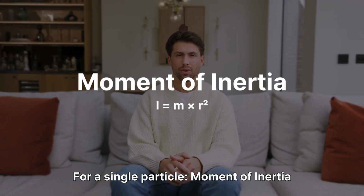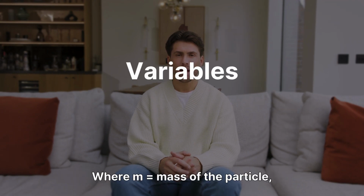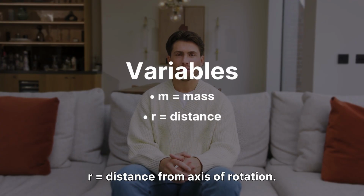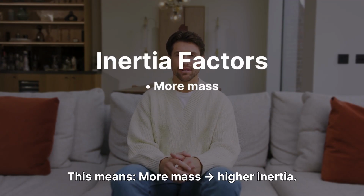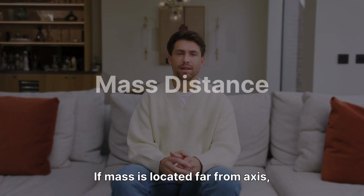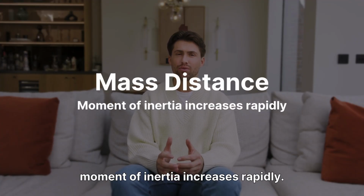For a single particle, moment of inertia I equals m times r squared, where m equals mass of the particle, r equals distance from axis of rotation. For a complete body, I equals the sum of m r squared. This means more mass, higher inertia. More distance, much higher inertia. If mass is located far from the axis, moment of inertia increases rapidly.